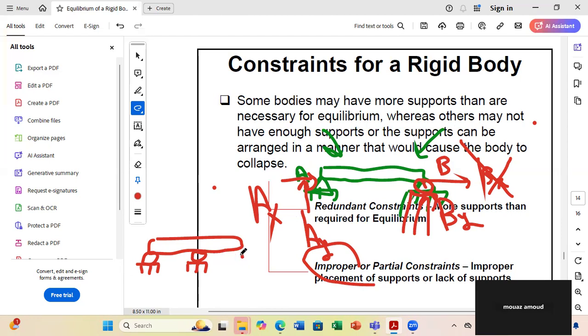No, because if a force comes in the x direction, it will move. Very good. If I put a force here in x direction, what will happen? A roller cannot develop a reaction in this direction. The three rollers will develop vertical forces here, so they cannot oppose motion in x. So for this scenario, it's not possible to have equilibrium.